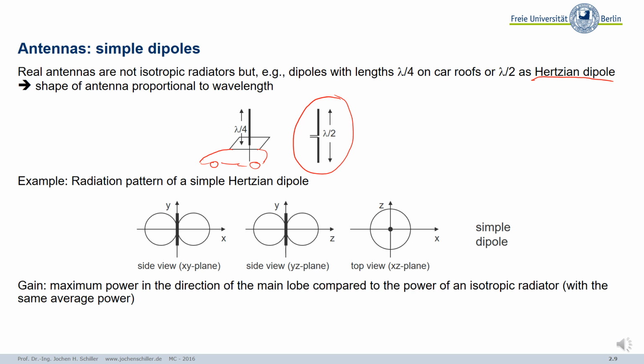But you could reuse the same antenna for GSM and LTE if the frequency ranges are close by. They are not optimal, but okay. And you can fine-tune these antennas with some electronic help. But these are the classical antenna designs.